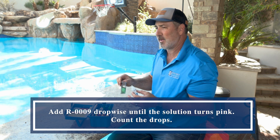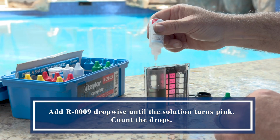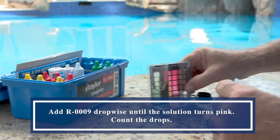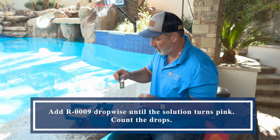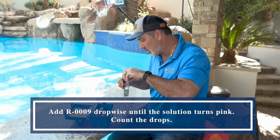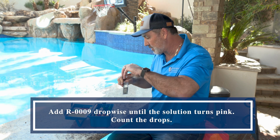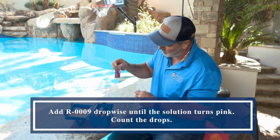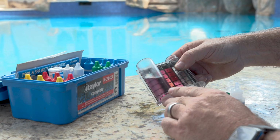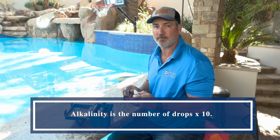So my alkalinity I'm expecting to be somewhere around 100 to 110. So I'm going to start with 5 drops. As you swirl this, you can see it kind of turns pink at the top and then it goes back to green. I'm going to add 3 more drops, so I'm up to 8 drops. Now it's getting light green. 9 drops. It turns pink, but it turns back to gray, and then 10 drops. See how now it just barely stays pink. So 10 drops times 10, so my alkalinity is 100 parts per million.